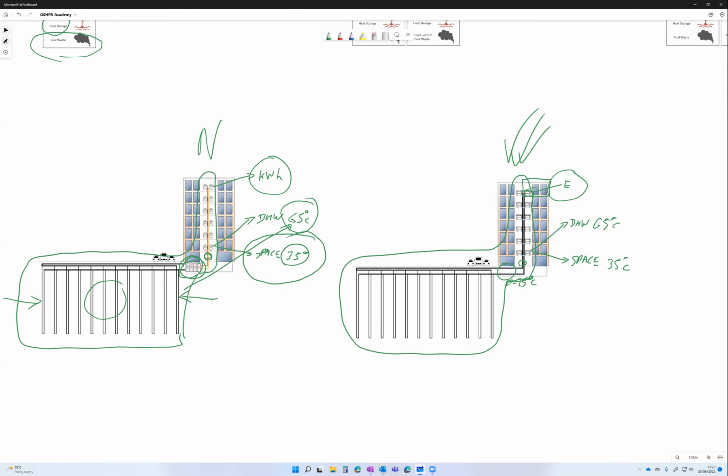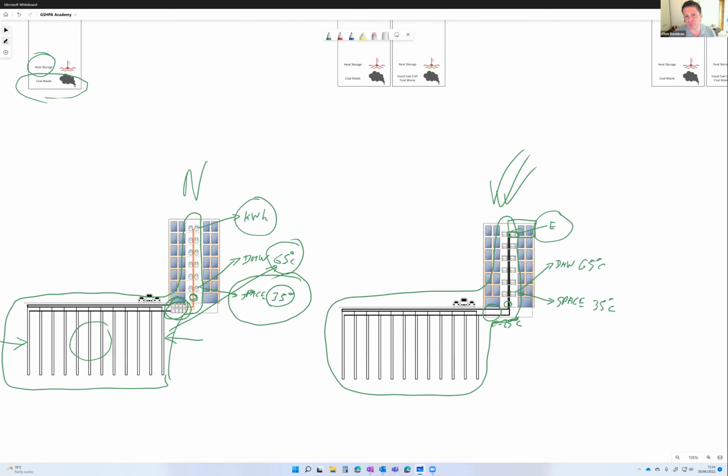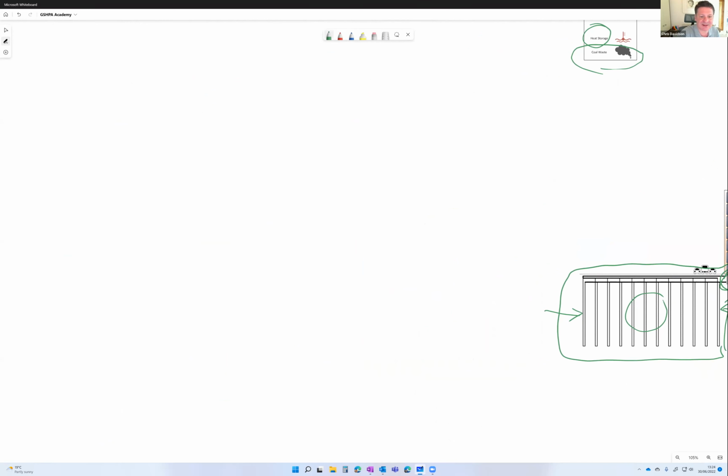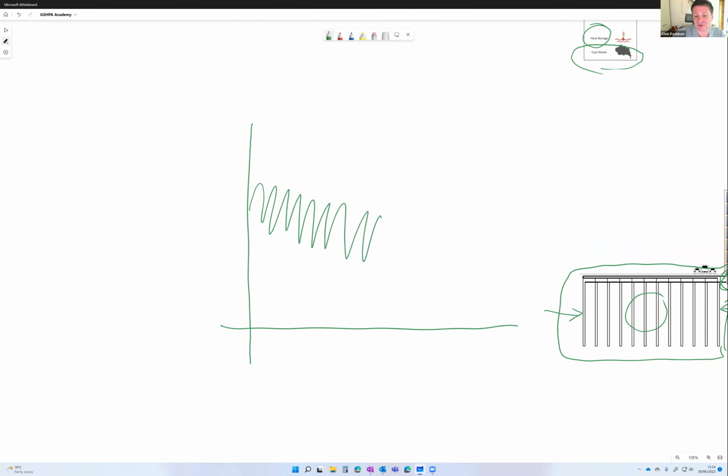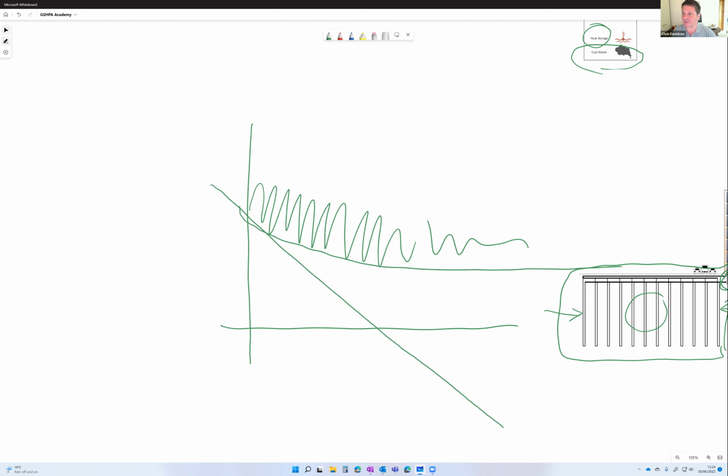And in regard to soil saturation, that's the second part that's just come through now. I don't really want to go into ground loop design too much today, but no matter what you're doing with a ground loop, you must ensure that it's sustainable in the long term. If we look at a heating only system, the temperature in that ground loop will do something like this between winter and summer. What we don't want is to see it just keep going colder and colder. We want this design to be tending to a limit, and that limit needs to be well within the capabilities of the heat pump. So that's the kind of parameters we put on ground loop design.